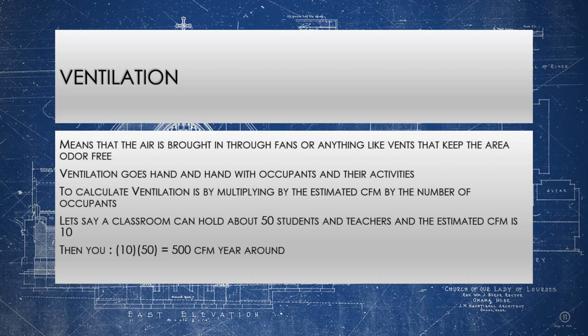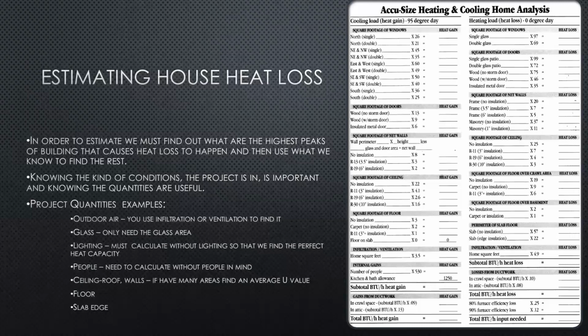So let's say there's a classroom that can hold about 50 students and teachers, and the estimated CFM is 10. You multiply 10 by 50, which equals 500 CFM year round.